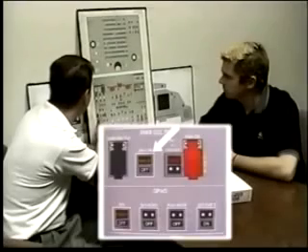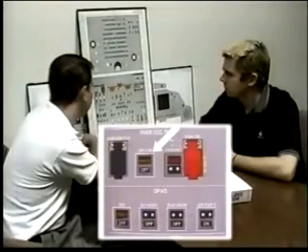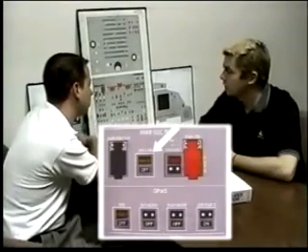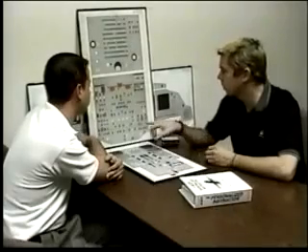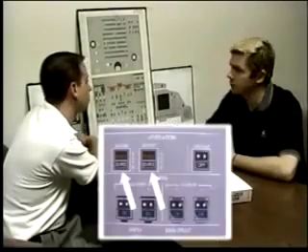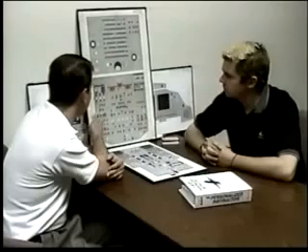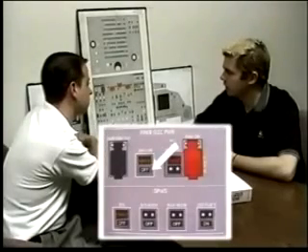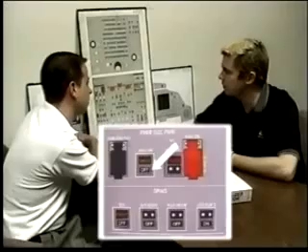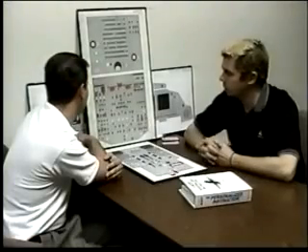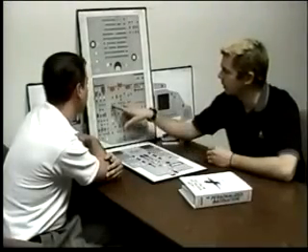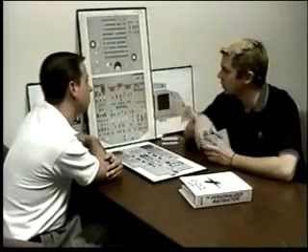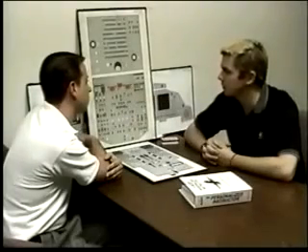Gen 1 line. You get smoke in the Gen 1 line switch. What does that indicate? There's smoke in the avionics bay. It's going to be associated with a blower fault and an extract fault as well. What occurs when you select the switch to off? The generator 1 disconnects itself from the AC bus 1, and it allows the number 1 pump in the left and right wing tanks to be powered from the generator.